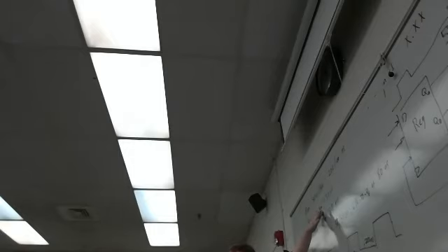The fetch and decode might be sequential or combinational, and really they're usually a mix of them from what I've seen. So you'd set those up with combinational logic, but it's too fast essentially. So you need to separate them by a sequential logic in order to deal with the clock. Okay.